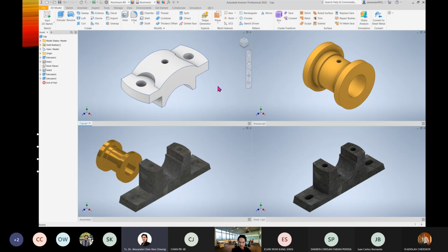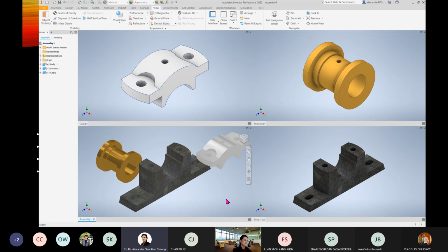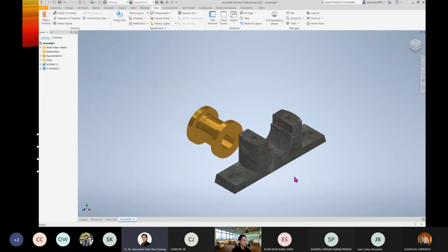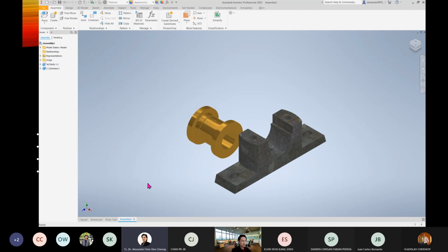With certain CAD software you may directly drag the part from here, but too bad, Inventor doesn't offer that. So you have to click the part in the design tree to drag it. Of course, if you're doing this, you may feel it's a bit tedious. But there's also a traditional way to place the file. Now I maximize it. Just now that was drag and drop, where you open all the windows. But if you want to do it the traditional way, you can also use Place at the top there.